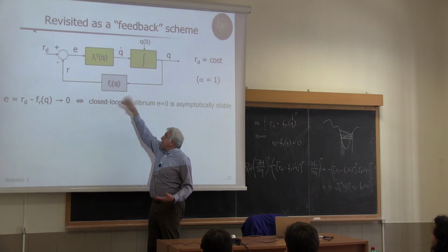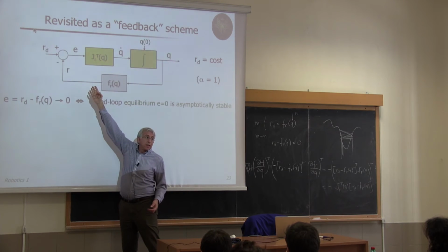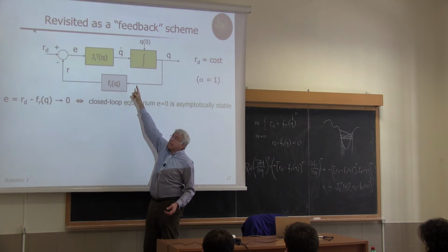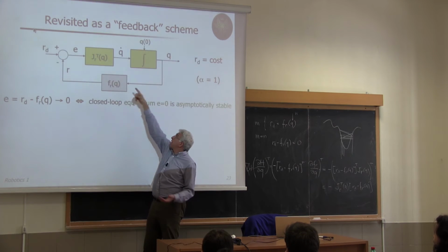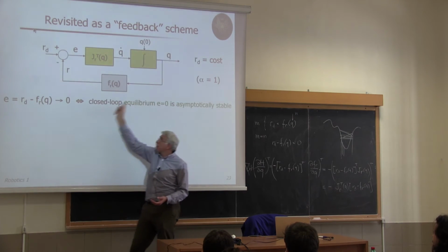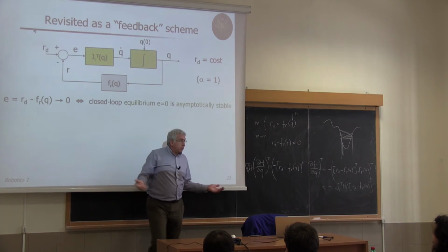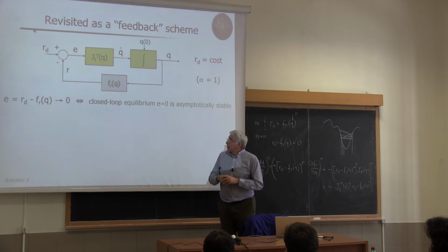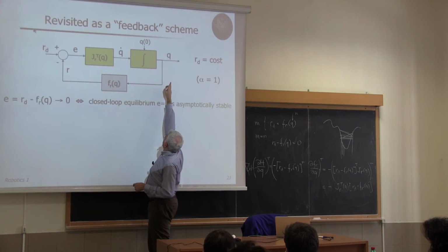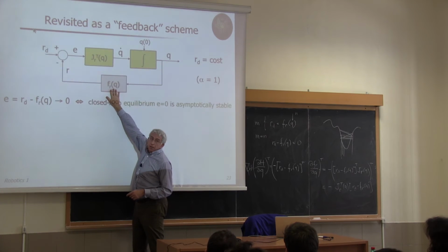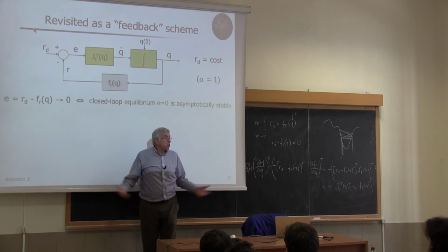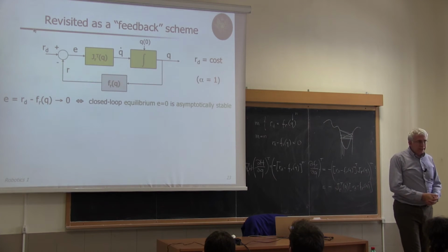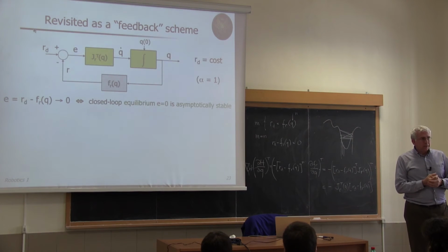Okay? So if this converges, or the system is asymptotically stable, we are in an equilibrium, and the equilibrium is E equals 0, because if E equals 0, J transpose of E is 0, then the velocity is 0, so we are not moving, we are not integrating, we remain in the same configuration, which generates the same value, which is 0. So this is the equilibrium. If this equilibrium is asymptotically stable, then automatically we will find there the inverse of this applied to the desired value. So exactly we are solving the inverse kinematic problem. Okay? This is the way of interpreting this feedback path.